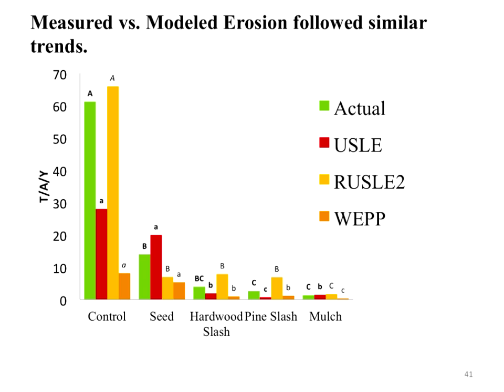And the interesting thing here was that when we compared our actual value of sediment versus 3 commonly used models, USLE, Russell II, or WEP, what we see is that none of them worked perfectly in all cases compared to the actual, but they all predicted roughly the same trends. So again, these models are useful tools for comparing treatments, not necessarily predicting erosion, but comparing treatments.